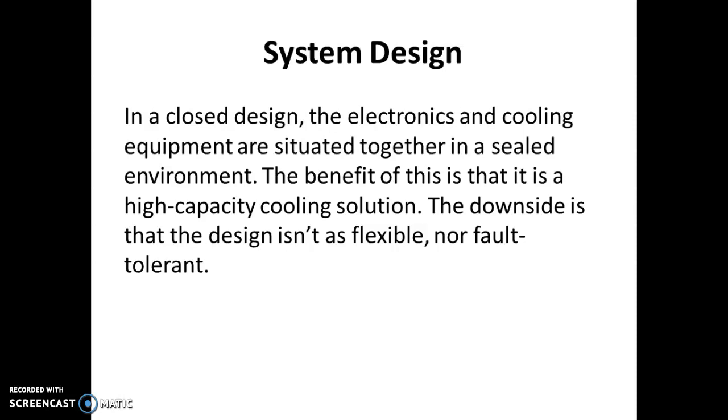Total occupant BTU is the number of people located in a particular room times 400. Basically, in a data center, there will be no people located in a room. Equipment BTU is again the total watts of power being consumed by all the electronic equipments except lighting equipments. So the total heat load can be measured as the sum of room area BTU, window BTU, lighting BTU, equipment BTU, and total occupant BTU.